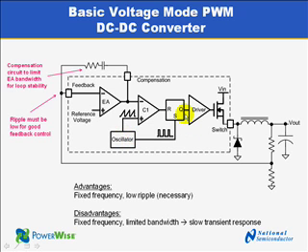This results in an overall rectangular fixed frequency waveform, but the on-time is adjusted by the error of the output voltage. In total, the advantages of the voltage mode are a fixed frequency and low ripple at the output. The disadvantage is that this fixed frequency, together with a limited bandwidth, results in a slow transient response.